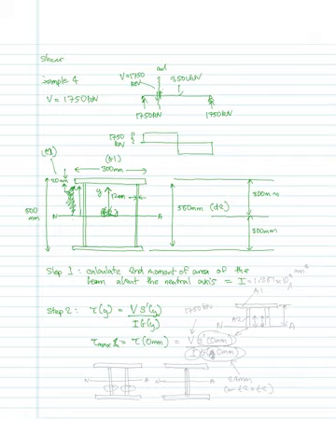So at the neutral axis, the shear stress would be maximum, and that would be equal to V S dash y, at 0 millimeters, divided by I, multiplied by b as a function of y, which also would be at 0 millimeters.